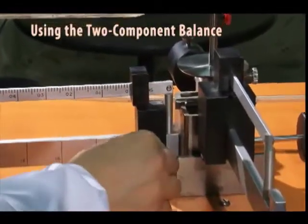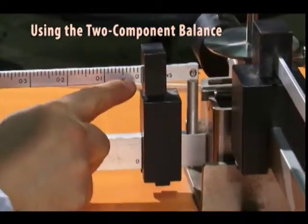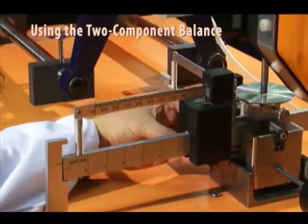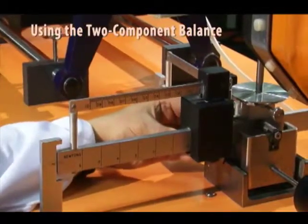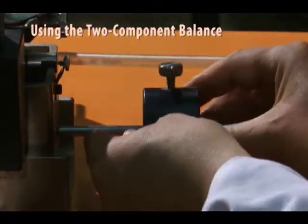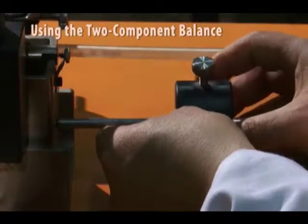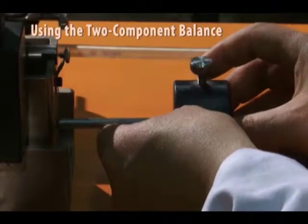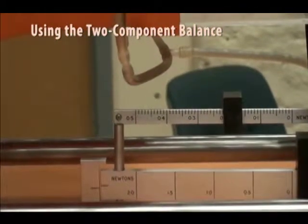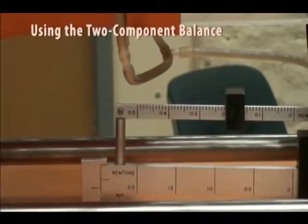Using the two-component balance. The wind tunnel is equipped with a two-component aerodynamic balance that measures both the lift and the drag components of the force exerted on the model under testing. The two-component balance consists of a pair of balances supported on knife edges on mutually perpendicular axes parallel to and normal to the axial center of the tunnel.